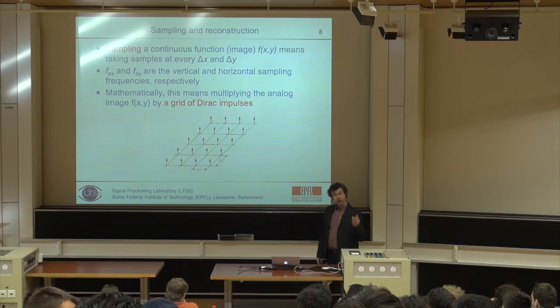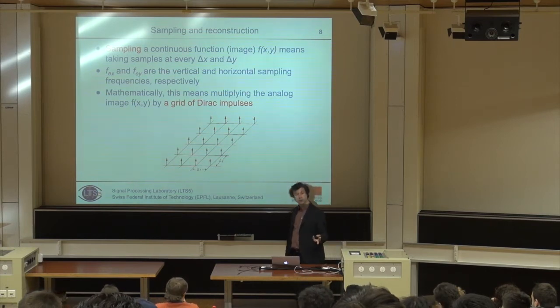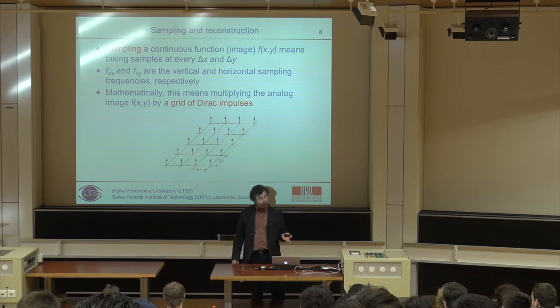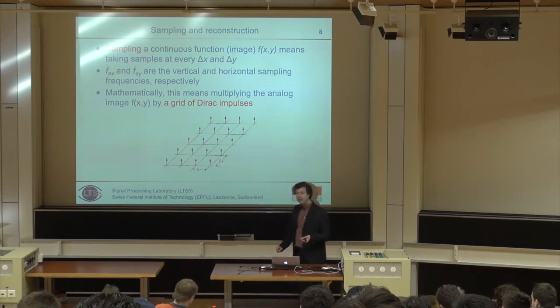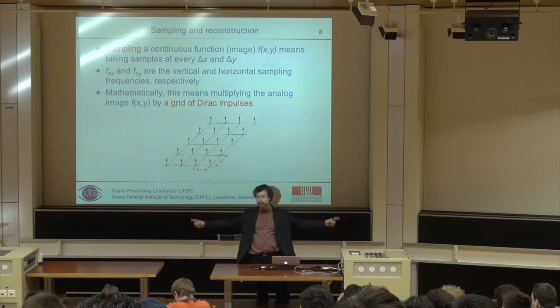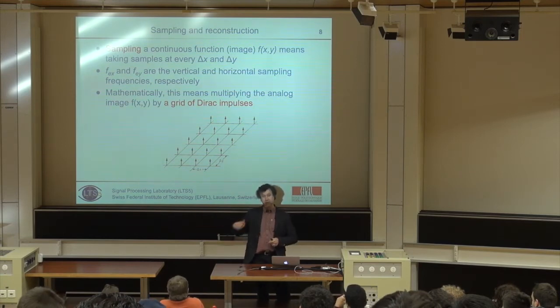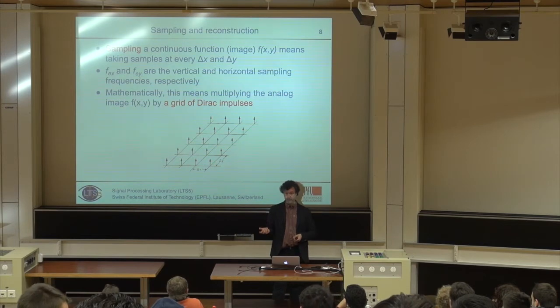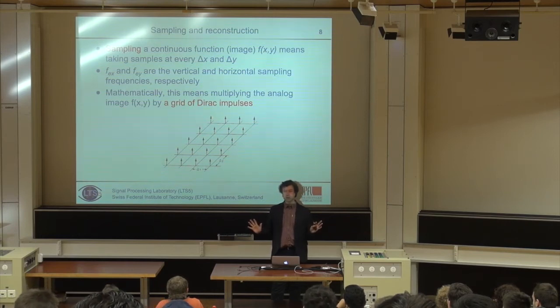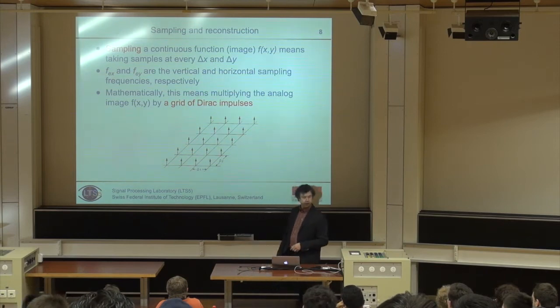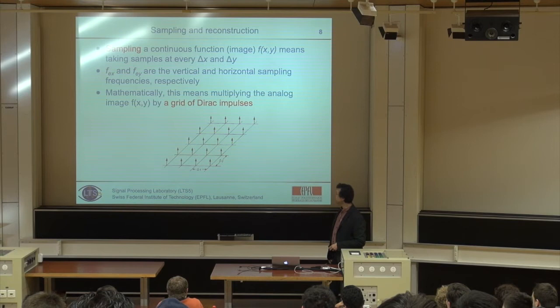And so basically, you know what happens when you sample an analog signal. In 1D, you remember that when you sample an analog signal, the spectrum gets replicated with a period corresponding to the sampling frequency. Clear for everybody? You remember Shannon's theorem? Sampling theory is clear for everybody? Yes? For whom is it not clear? Otherwise, you Google sampling and Shannon and you will find.